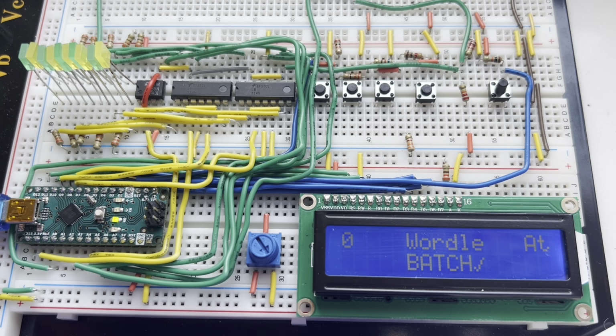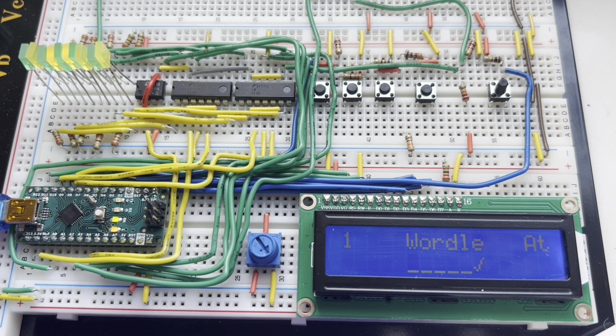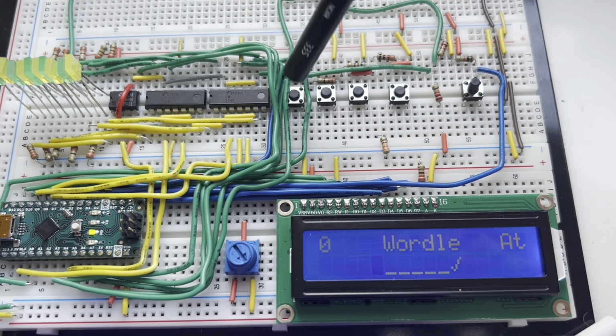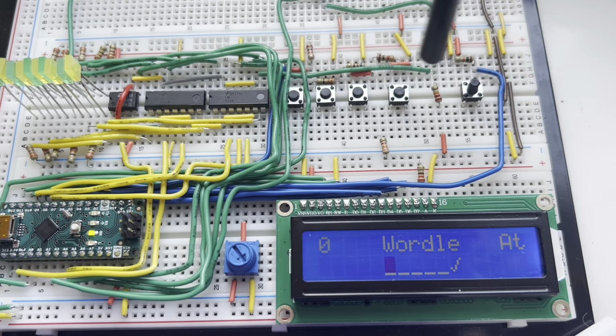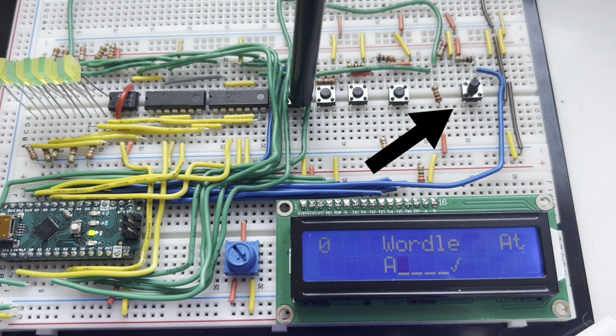Furthermore, the buttons are connected to pin 2, an external interrupt pin. An external interrupt pin on a microcontroller is a hardware input that triggers a specific action or routine when a particular event occurs, such as a change in voltage or signal. It allows a microcontroller to respond immediately to external stimuli without continuously checking for changes, enhancing efficiency in embedded systems. Pin 3 is also an external interrupt pin for the Nano, which the select button is hooked up to.